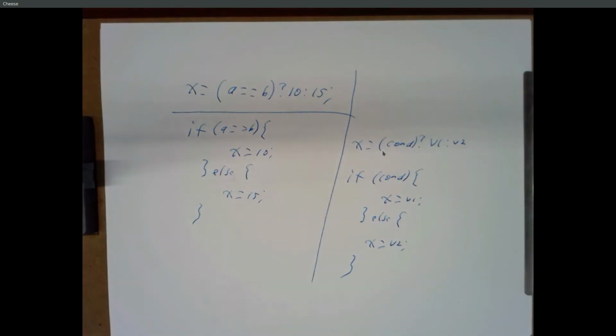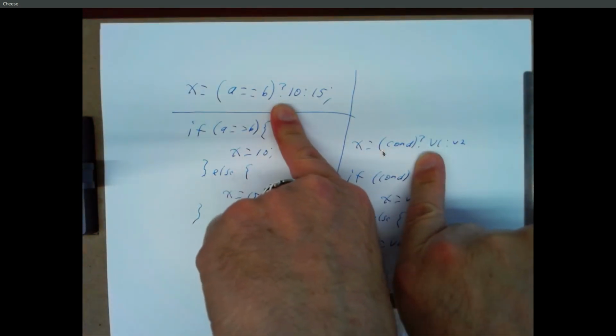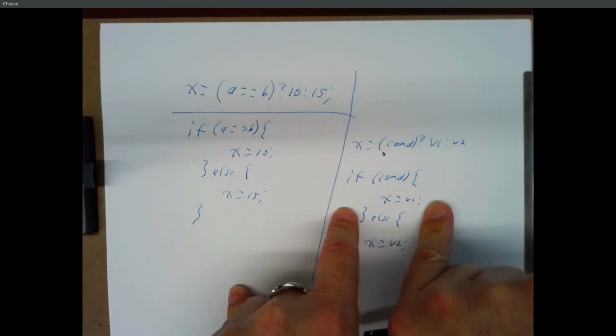So in C, you can just write an if statement, right? And it's almost always as easy. In Verilog, we can actually use this ternary operator, this question mark, in an assign statement, which means we can squeeze these if-then statements into a single assign.